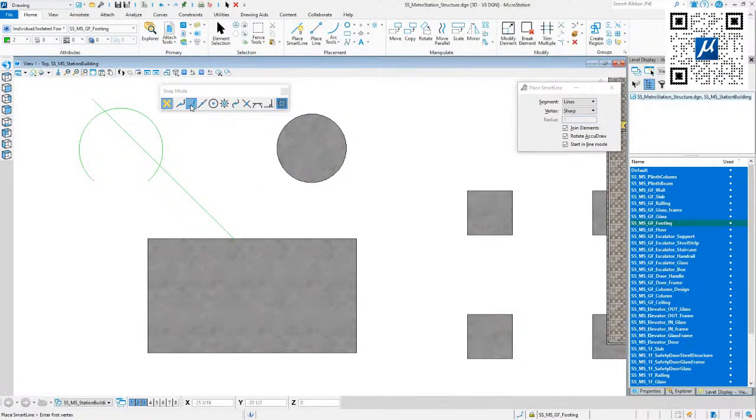And last but not least, let me show you something with a key point. We have some shortcuts from the keyboard. You could activate the intersection using an I, or C for center snap, and K for key point. And key point is special. If I type a K on my keyboard, then I get a key point snap divisor.